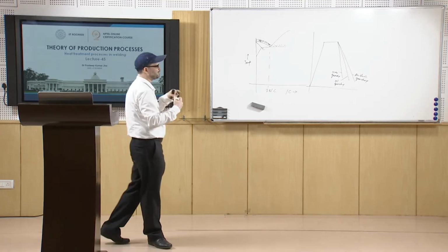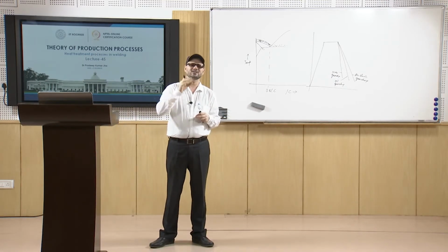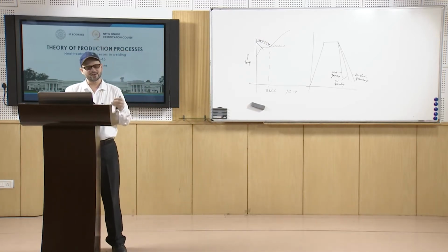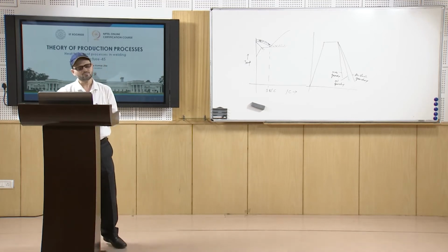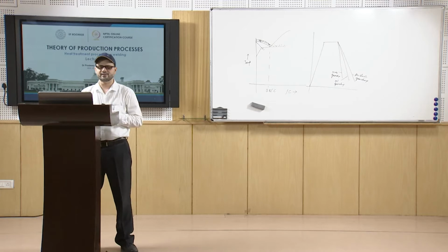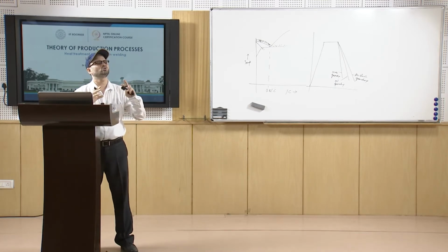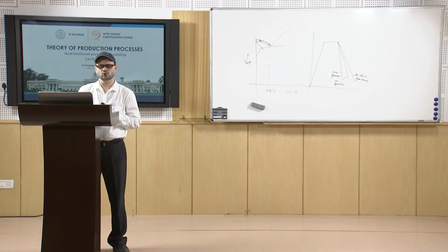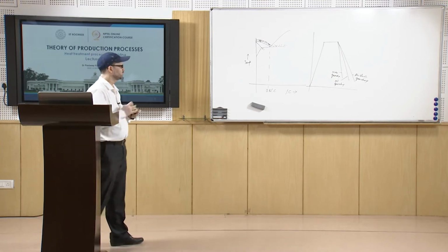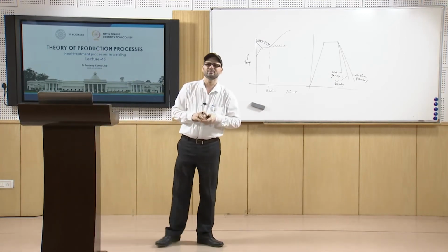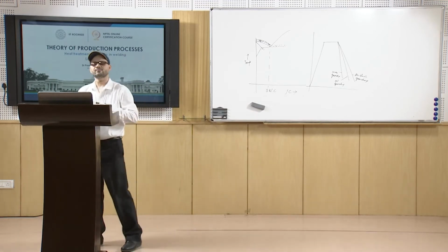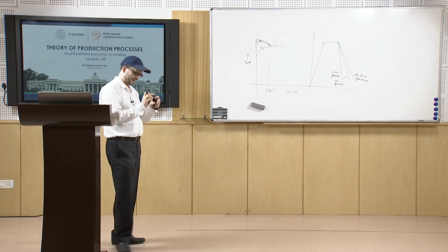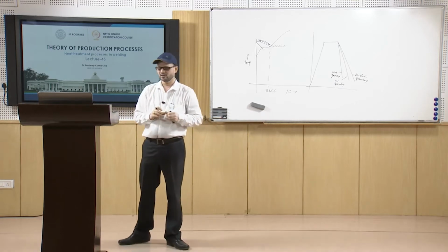By tempering, the ductility and the toughness properties are improved, and the extremely high brittleness is reduced. Now, many a times we also do tempering in the temperature range of about 260 to 310 degrees centigrade, and that shows a loss of toughness. If you temper in that zone, we often see that the toughness is decreased. That temperature zone is known as the brittle tempering range.